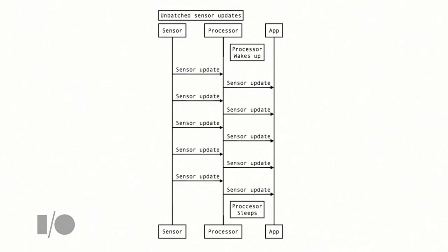It consumes a lot of power and is incredibly powerful computation, but is also very power hungry. It has to stay on for a few seconds, even if it needs to do a little bit of processing. It needs time to wake up and sleep. If every time you get a sensor measurement, you wake up the application processor, it never gets a chance to go to sleep. So getting the application processor to sleep is a key power savings technique.